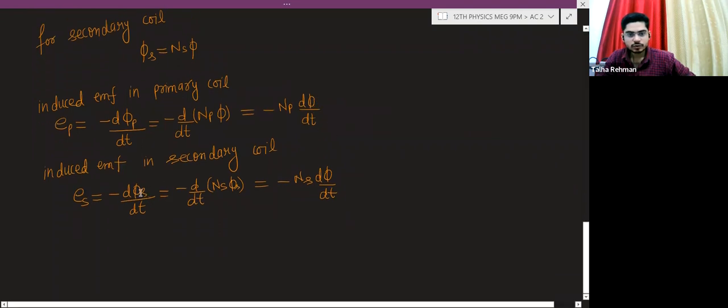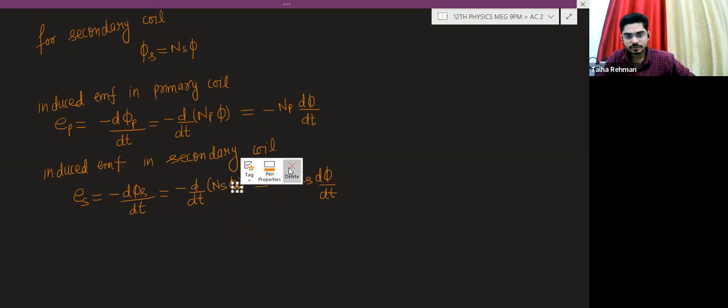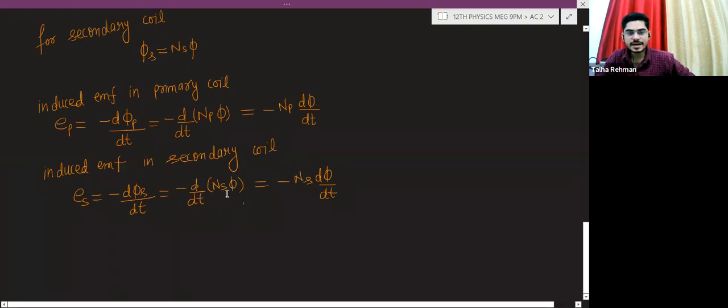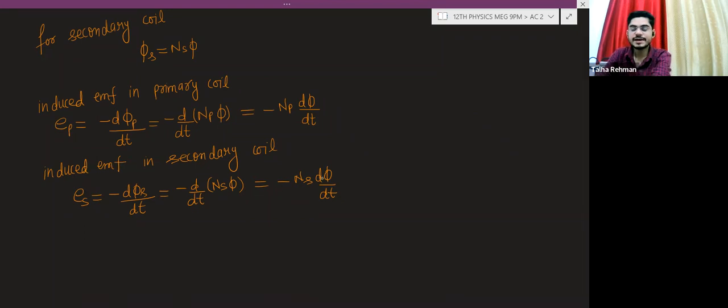What is phi s? Phi s is Ns into phi. So in the secondary coil, the EMF induced will be minus Ns multiplied by d phi by dt.